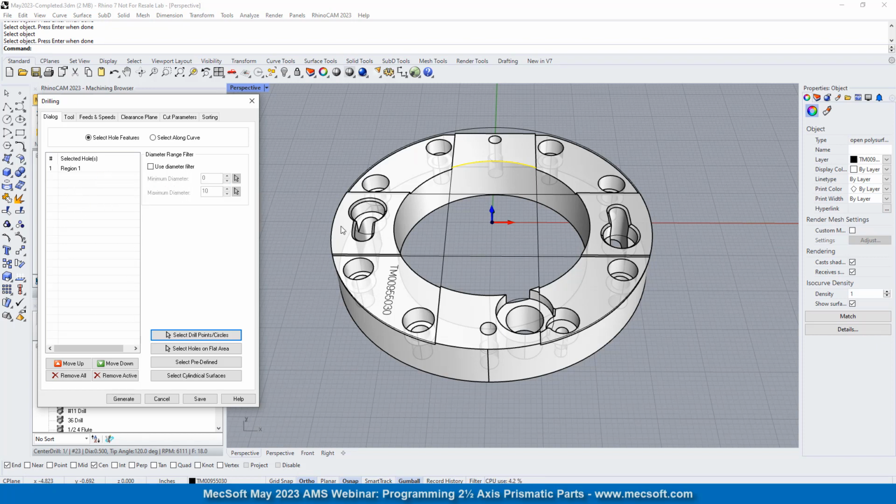And also, I want to mention here, when you drill, you have to select a circular edge, an arc, a circle, okay? It has to be either an arc or a circle or a point. No curves, no spline curves, nothing that is not recognized as an arc, a point, or a circle. Okay, so we selected a circular arc. It'll automatically determine the center point for us.